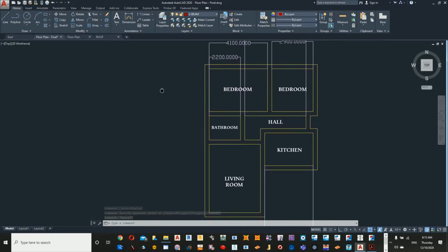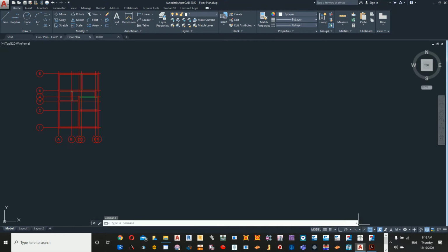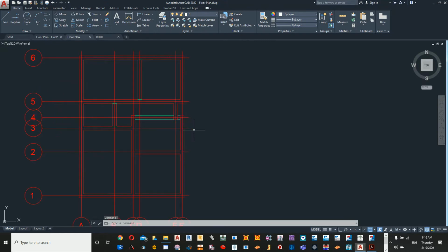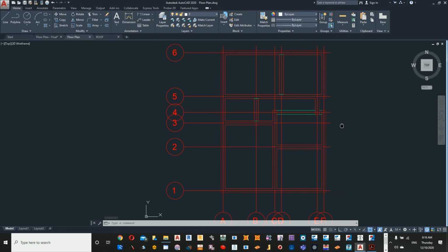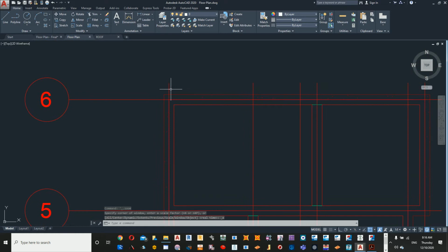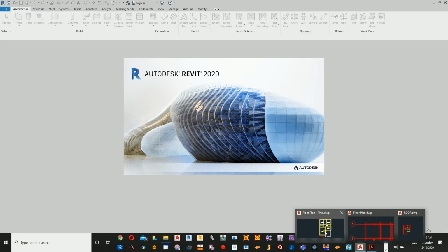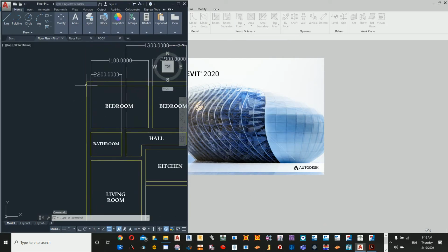Okay. So we can have this one directly. Okay, but once again we need to measure from the center to the center dimensions, center to center dimension. Let me see the other. This one might be a little bit easier since I have drawn already the grids. Since I have already drawn the grids, what I have done, when I receive normally a CAD file, I draw the inner line, which is the center. Okay, and I keep copying it all over whenever, like for example, this wall now.